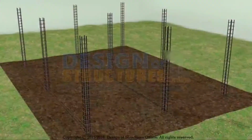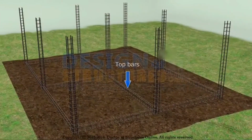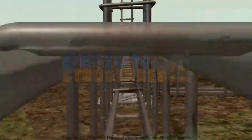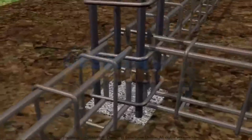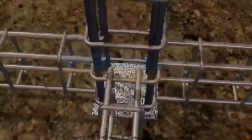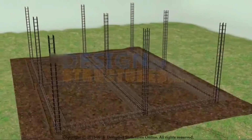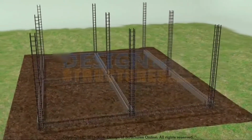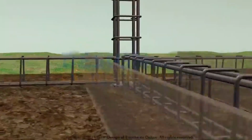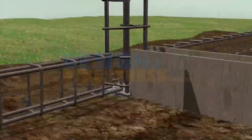Beam reinforcement shall be as per drawings. Top bars, bottom bars and stirrups to be placed with proper development length. Joints in the beam shuttering should be tight against leakage of cement grout. Construction of shuttering should permit removal of various parts in desired sequence without damage to the concrete.